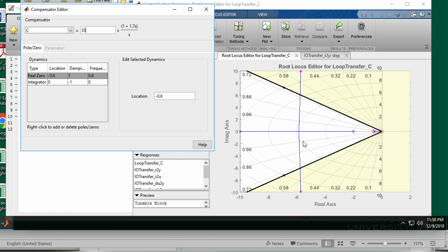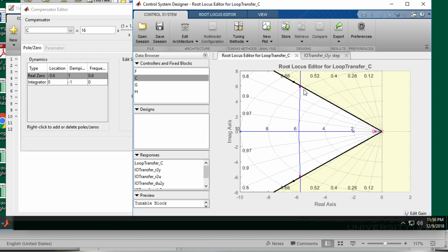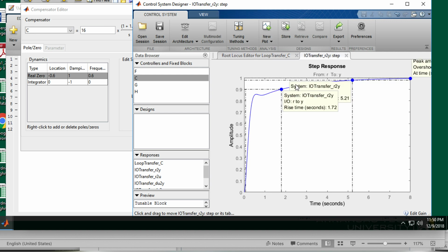And this is the root locus. Root locus really allows us to see our lines of constant damping ratio and our lines of constant % overshoot. So we can really see what design conditions we're working within and see our poles and our zeros of our transfer function. And right here, just kind of playing with these KP values, these proportional constants. If I start this out at 16, I can show you the results we get from that. And go ahead and look at the step response.